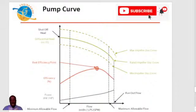Now we have other parameters on the pump curve, such as the best efficiency point, the shut-off head, efficiency, power, minimum allowable flow, run-out flow, and maximum allowable flow. You can see about 3 curves.